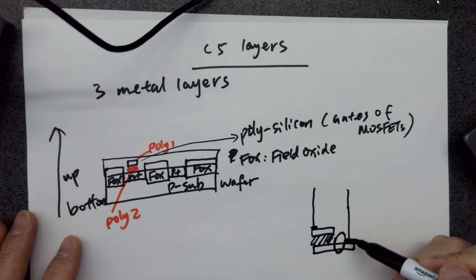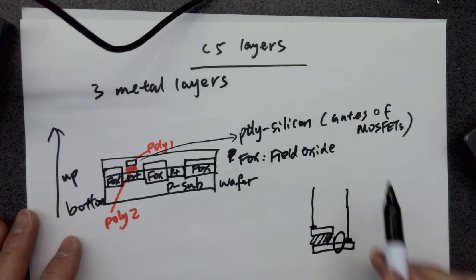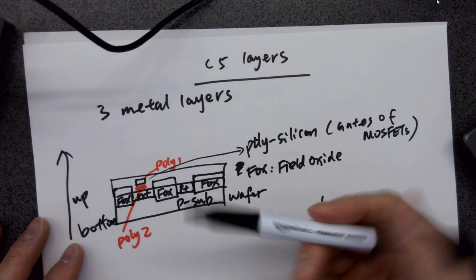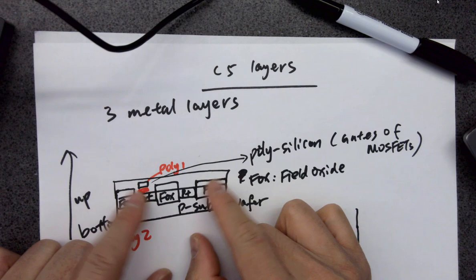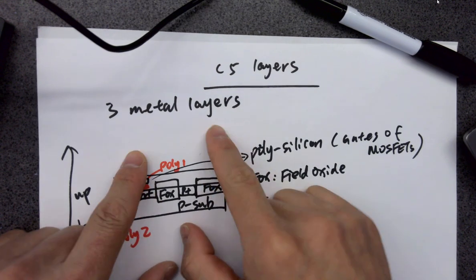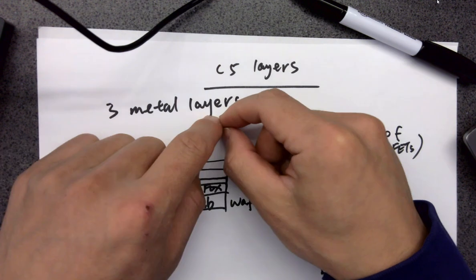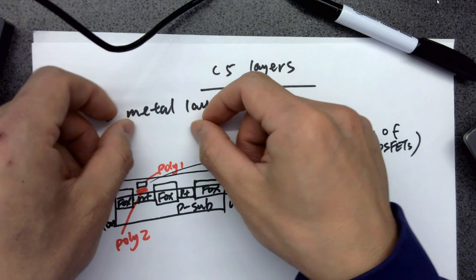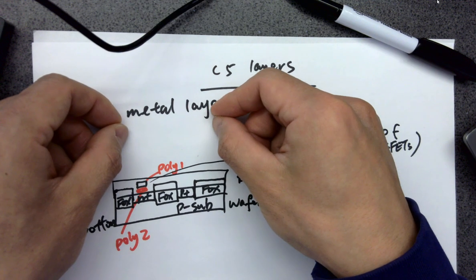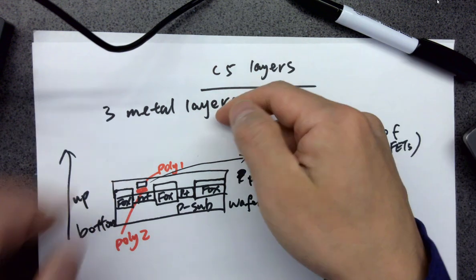The reason we have to get all the wires going up is because all the chips have all these intermediate layers of metal, and there won't be any access to the middle layers. Eventually, you have to build all these layers, and on the very top of the chip, you have a little opening, and you can use a wire bonder to bond it to the top metal pads, and eventually either inject signals into the chip or probe it from all these pads.